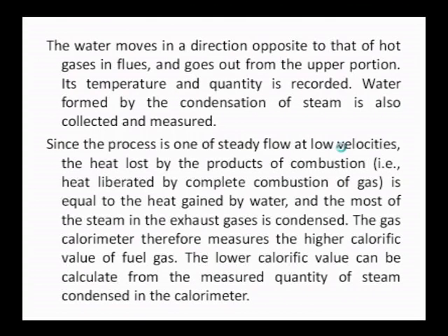The water moves in a direction opposite to that of the hot gases in the flues. When the gases move in one direction, the water moves in the other direction and goes out from the upper portion. Its temperature and quantity are recorded. There is a provision for recording the quantity of the particular fluid and also to measure its temperature. Water formed by the condensation of steam is also collected and measured in the system.